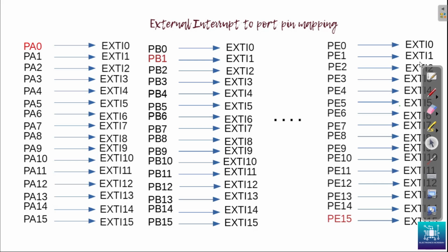Now let us quickly revisit the slides that we had seen previously for external interrupts. The reason we are doing it is that a little bit of recap is necessary, because the external interrupt setup is a little bit more complicated than the SysTick interrupt setup. We will be using the EXTI0 interrupt.